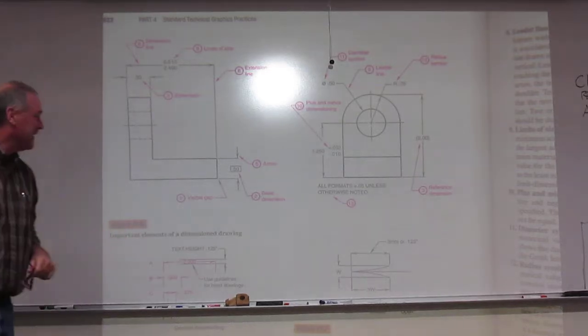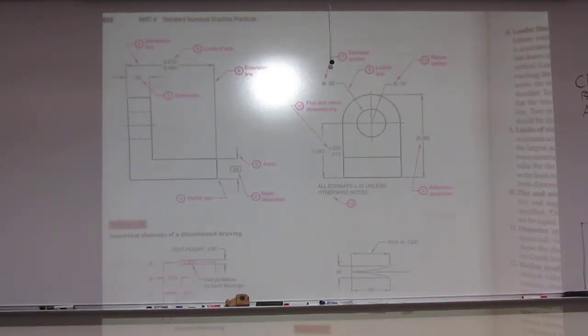All right, so that's a reference dimension. 4 is a dimension line. We've already covered that one. Any questions on that guy? Okay. 5 is the arrows. We've already covered that one. 1/8 inch. Width is always length divided by 1/3, closed filled arrow.